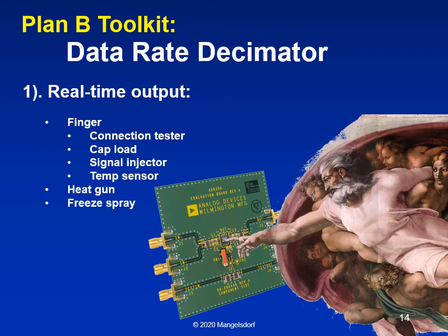and that can actually slow you down because there are a lot of things that you just want to try real quick and see what happens to the signal. For example, I believe that the most important test tool that we have is our fingers. You can check connections by just pushing on elements, for example, if they're not too hot or too high voltage. It's a socket problem, a weak connection, something like that. You flex the board a little bit, you'll find it. And this happens all the time, but you can't really see that unless you're pushing on it in real time. It's very hard to find.